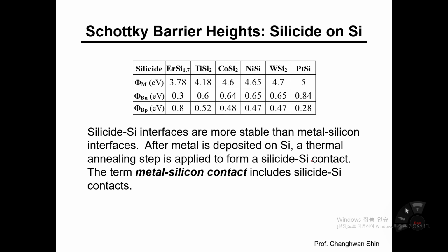Therefore, the work function of erbium silicide, or of a silicided material, is quite different from the work function of silicon and the work function of the pure metal itself. Many researchers have found that erbium silicide, titanium silicide, and NiSi are the mainstream currently used in the CMOS technology platform, tungsten disilicide is an emerging one, and cobalt disilicide is another new option.